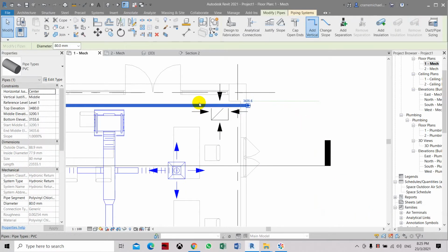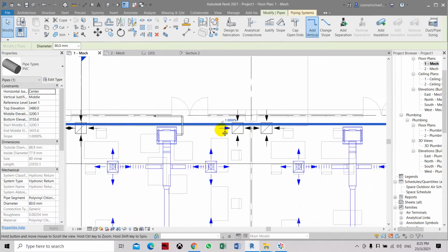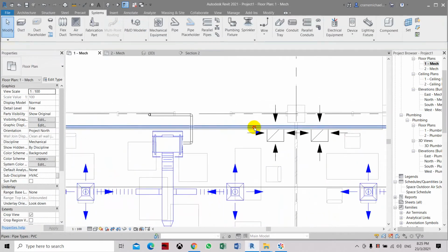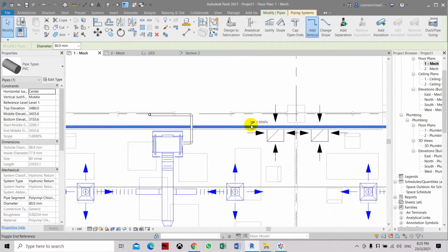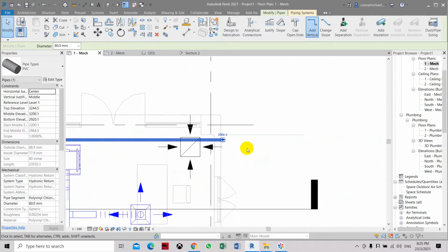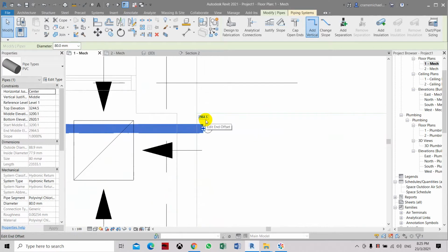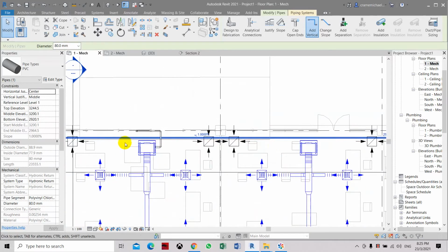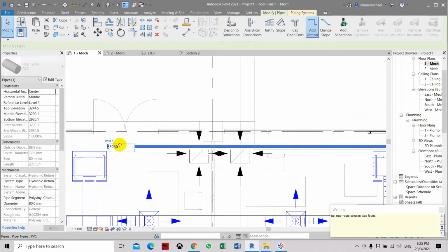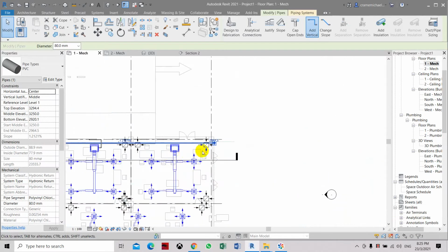So 3.435. Now it's in the opposite direction. Let's check this. Let's set it -1. Sometimes the -1, so it will be on the opposite. So this is the high level and it's going down to this low level. See, we have reached 2964, so we need to increase this height to 3250, so we won't be clashing with the ceiling level.